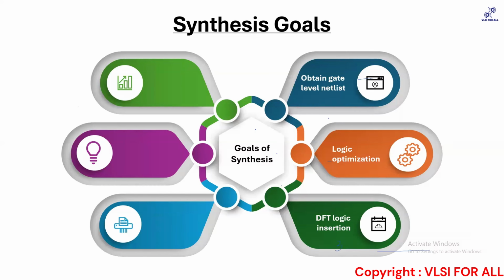Okay. If you get it as a part of synthesis, you can perform a resynthesis, an incremental synthesis using the compile command, so that now you can perform scan chain reordering, right? If you're doing a physical aware synthesis, as I stated, right? But then we can do scan chain reordering in the PNR stage also, during the placement stage.